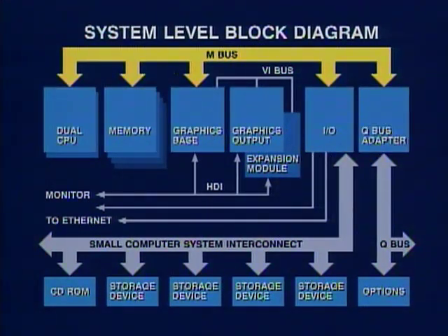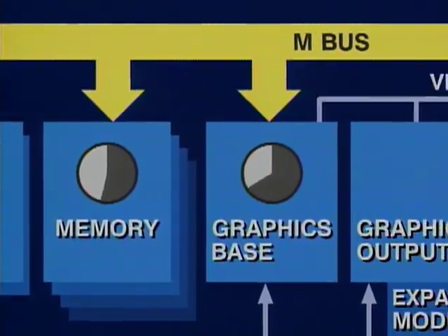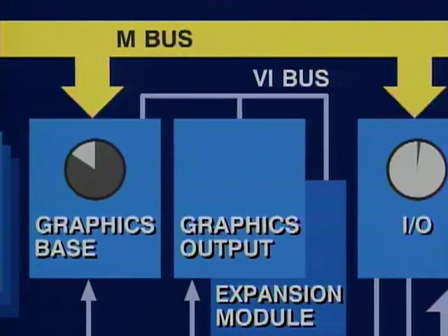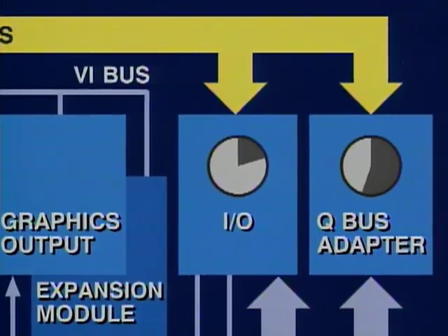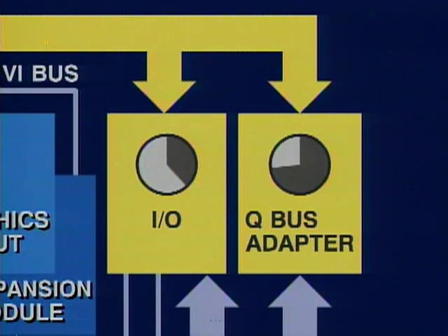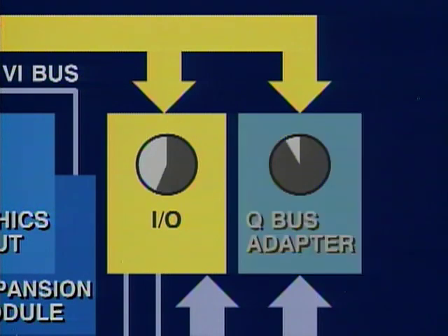The M-bus is a synchronous memory interconnect between the VAXstation modules. The M-bus supports a maximum of 7 modules that arbitrate for the M-bus using a least recently used priority distributed resolution scheme. In other words, each M-bus device has an interval timer that is reset when it becomes busmaster. When 2 or more devices request the bus simultaneously, control will go to the device that has the longest amount of time in its timer. A list of M-bus signal names and pin assignments are located in the appendix section of the VAXstation 3520-3540 maintenance guide.